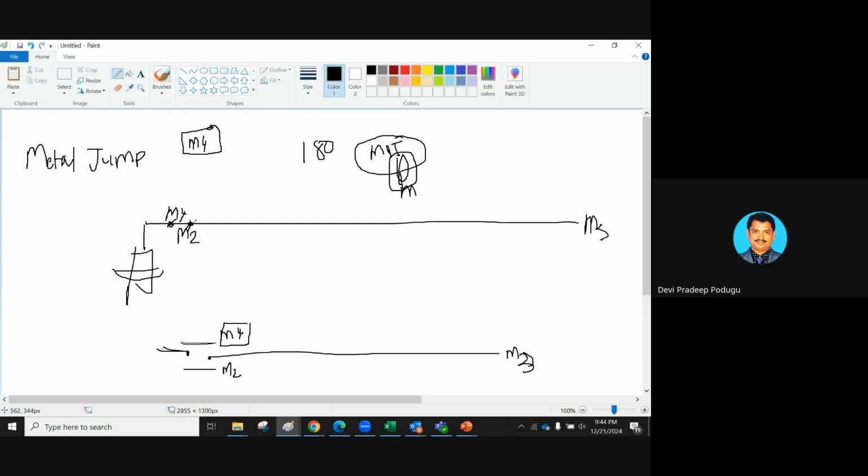Once again, the question. I am having some antenna violation. What I told about antenna violation is, if there is any longer metal connected to the gate, then at the time of the etching manufacturing process, while we are doing some annealing process, the larger amount of charge stored in this metal will try to go through this gate. So this current will damage this gate.